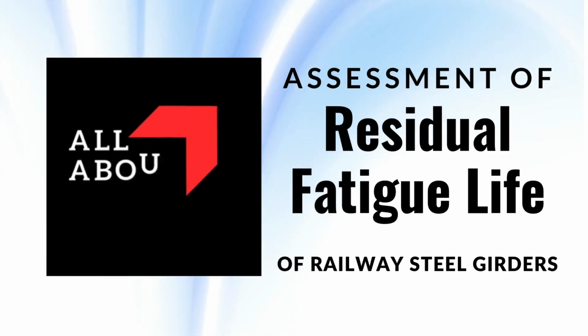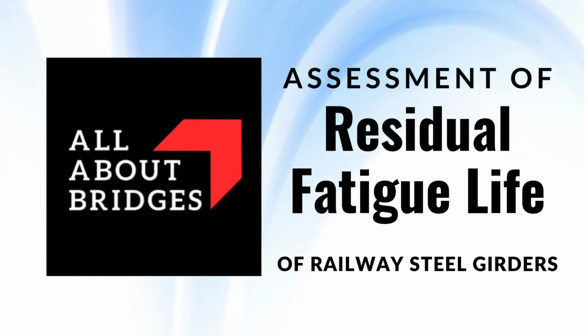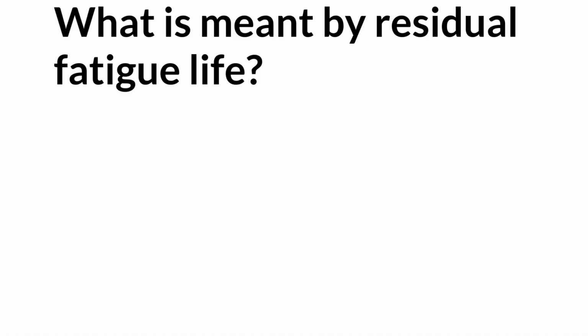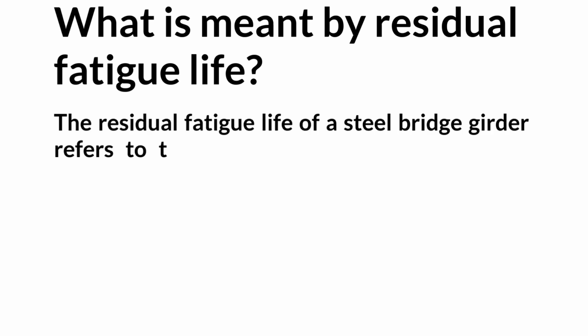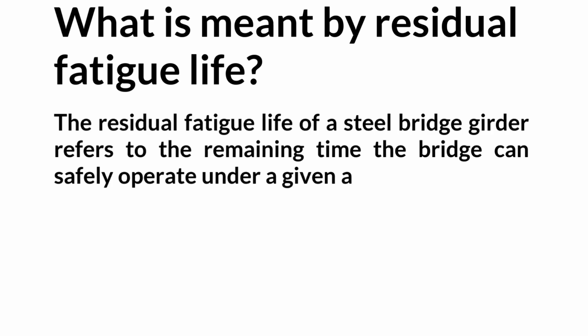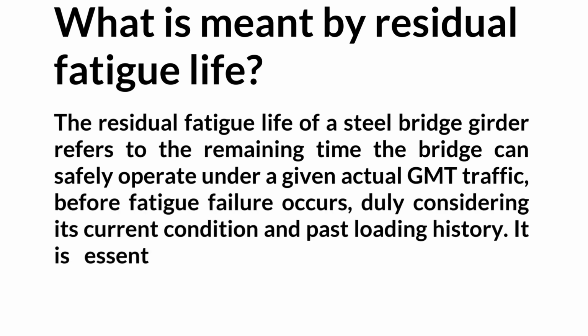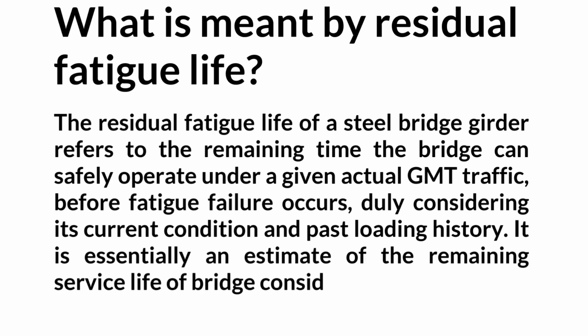Now coming back to the topic, that is the assessment of residual fatigue life by simplified approach. Let's first understand what is meant by residual fatigue life of a railway steel girder. The residual fatigue life of a steel bridge girder refers to the remaining time the bridge can safely operate under a given actual GMT traffic before fatigue failure occurs, duly considering its current condition and past loading history. It is essentially an estimate of the remaining service life of the bridge considering fatigue.